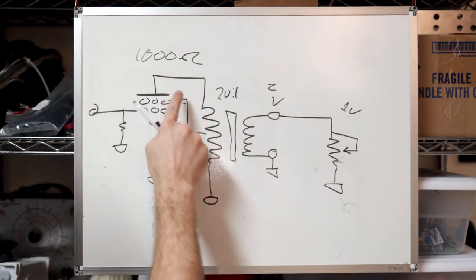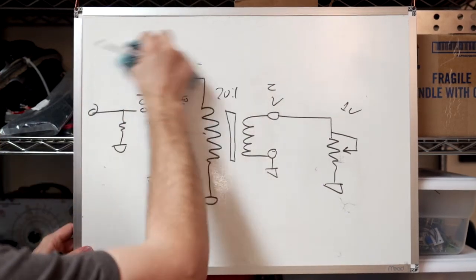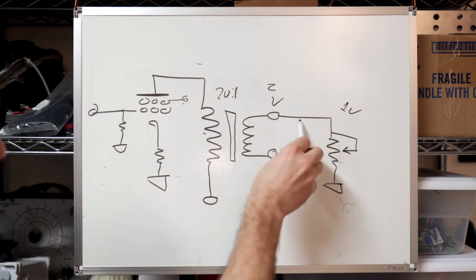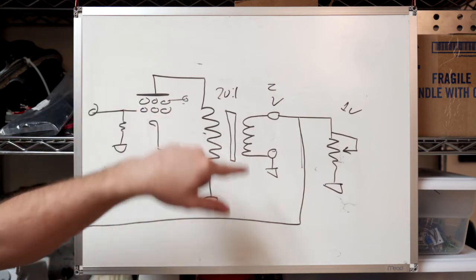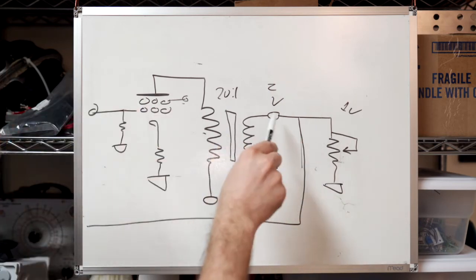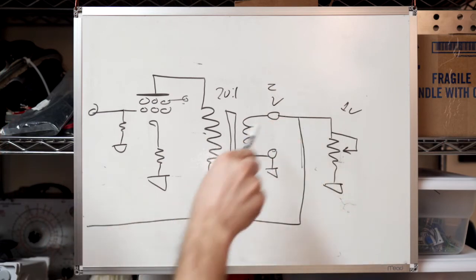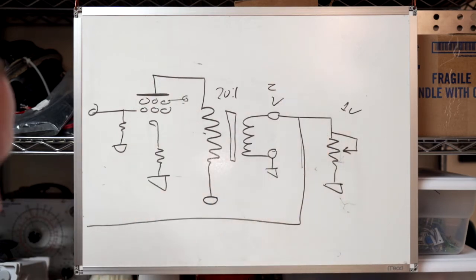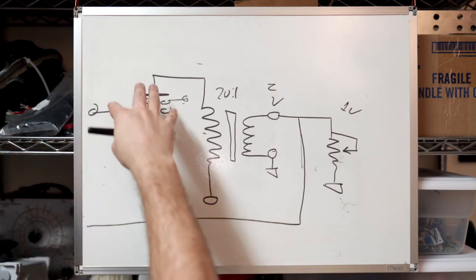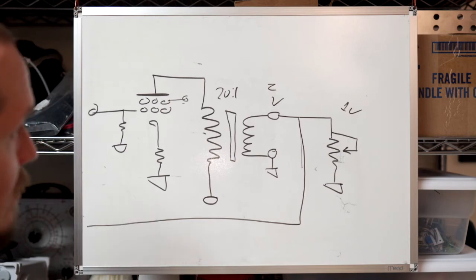You could also, let's say you're running pentode again, just for the sake of argument, change the output impedance by running loop negative feedback from here back to a previous gain stage, and the more gain you enclose within the loop, the more information you're injecting about the output voltage back to the input, right? And so it knows if the output voltage is dropping, and it adjusts the gain of the circuit. It amplifies the difference to try and maintain a voltage. So it makes it act more like a voltage source. And so that will also change the output impedance of the circuit.